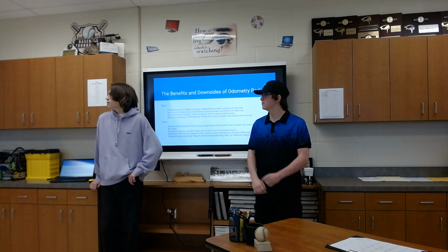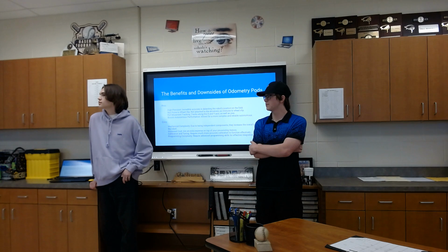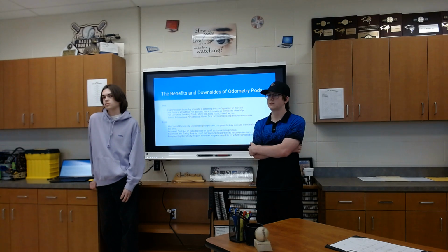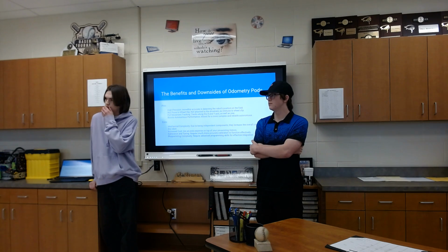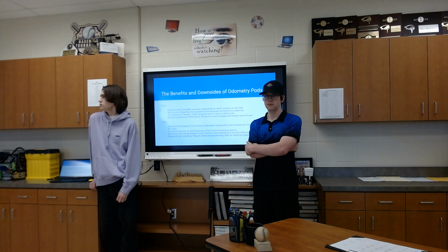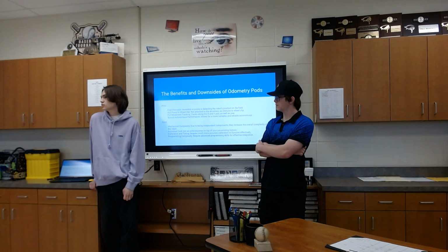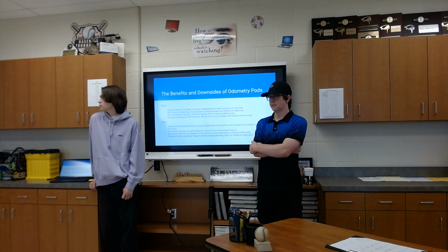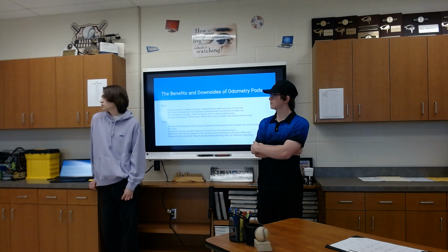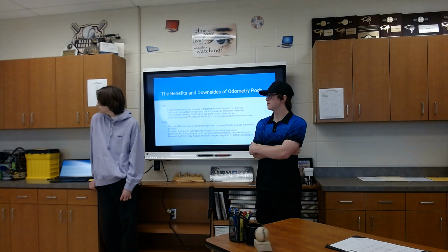So you guys are all probably using either goBILDA motors or REV motors, and they have the black cap on the end. Those are going to be the built-in encoders, and those can also benefit from Roadrunner. The difference between the dead wheels and the built-in encoders is, like they were saying, the odometry pods and the dead wheels are just more accurate because they separate out the slippage that you would get from the mechanism wheels.